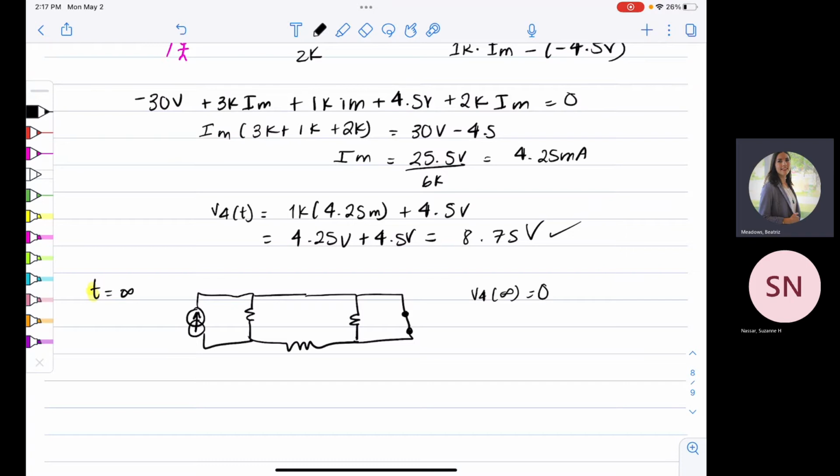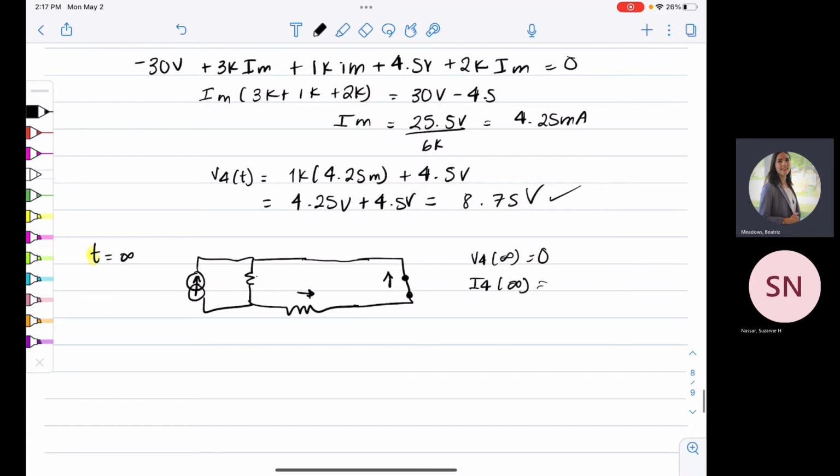So right off the bat, we can answer that question again. That's a freebie, but we do have to find the currents through our short, right? So when you have a resistor in parallel with a short, what happens? Right. So I'm just going to go ahead and delete that guy. So this is our network, right? So the current through here is the same current as this resistor, and I'm just going to go ahead and draw the circuit better.